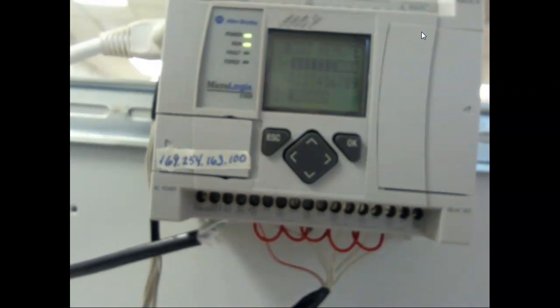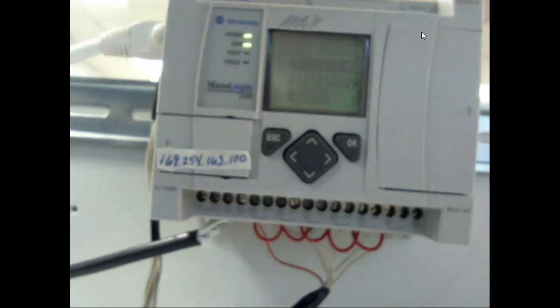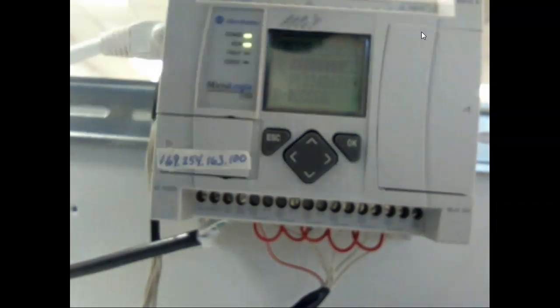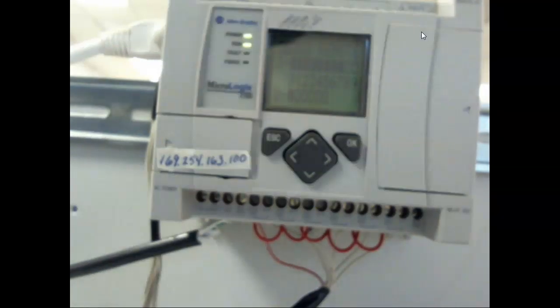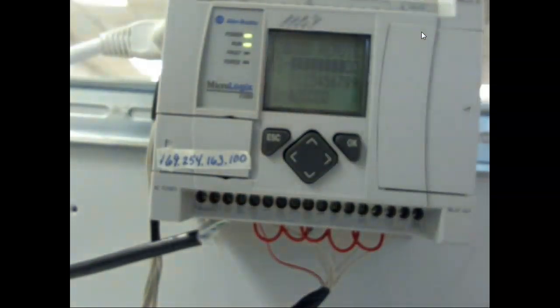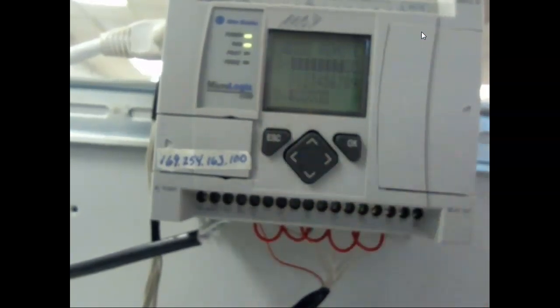So what you can do right off the bat is, a PLC will help you troubleshoot, because if I'm over there hitting the push button, then I should be seeing on my PLC that the push button's going through. So a lot of times we can check out the wiring of a circuit if we've got broken wires or stuff without ever getting the meter out. And it also shows me that output 0 is true. So output 0 is turned on, which is what we were using for the program.